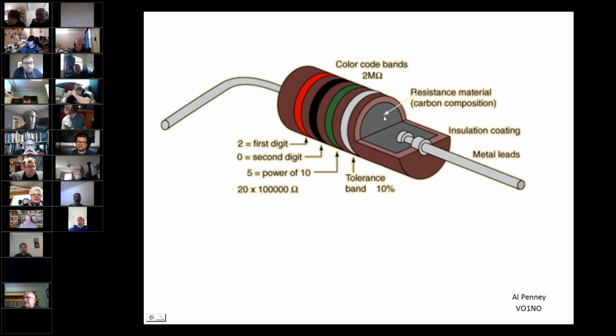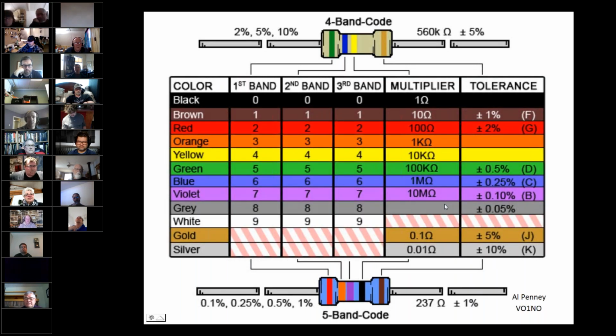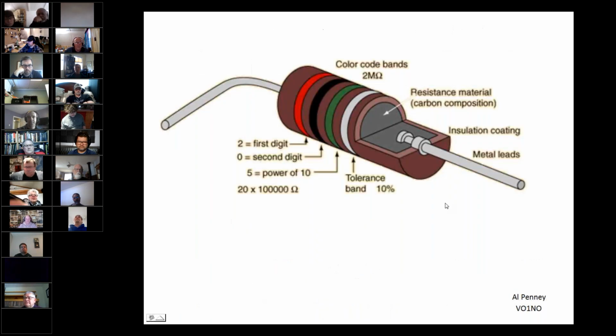So it could be some clay in there. And that's all encapsulated in this resistor. From here to the terminal on the other side, that would give the resistance as it travels through this carbon composition material. So the flow of electricity can flow on either end of the resistor. Yep. Electrons are going to enter here and go through and exit here, or they could enter here, go through and exit here. Okay. Resistors, it doesn't matter what way you put them in the circuit.